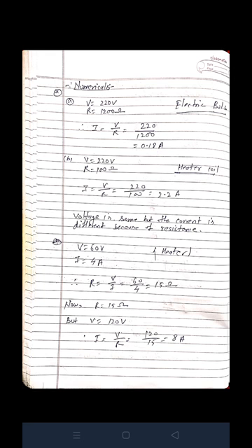Okay, so we know now that resistance is 15 ohm, but the next part is what? Suppose we are increasing the voltage to double, that is the voltage now becomes 120 volt. Earlier it was 60 volt, now it is 120 volt. Then what will be the value of current? So we know that I equals V by R. By putting all this, we can find the current is 8 ampere.